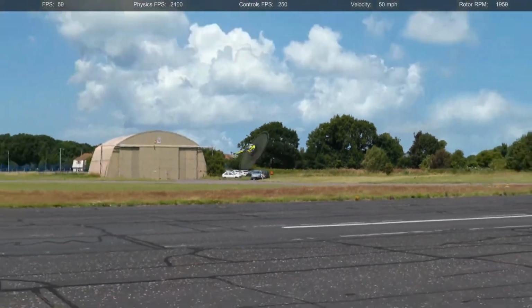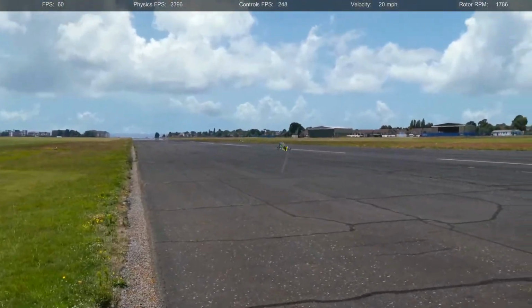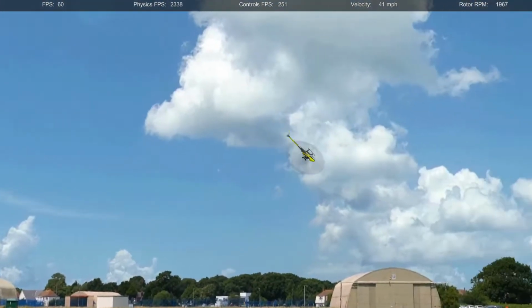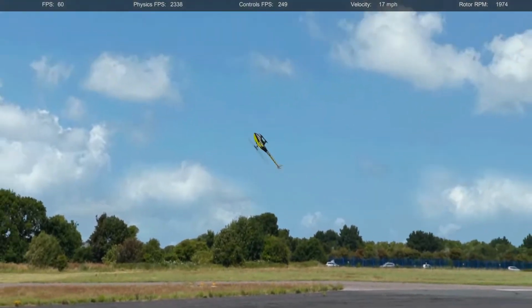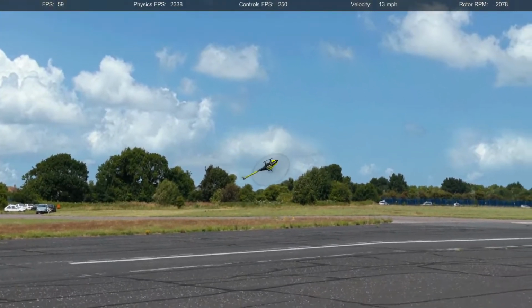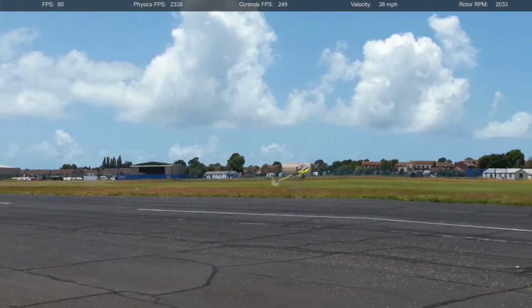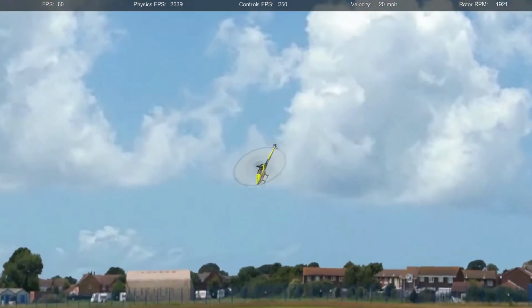So you have 3 choices. You can drag a vertical tail around with you all the time. By the way, do you know what a 737 tail weighs? It's about 8,000 pounds. That's 8,000 pounds of fuel you could have carried, 8,000 pounds of payload, 8,000 pounds of luggage or whatever.